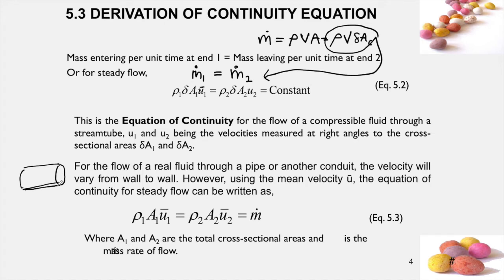So the fluid will stick at the inner wall of the pipe. From the front view, we can see that the fluid sticks on this surface of the pipe. Therefore, it affects the velocity gradient in a pipe, and it turns parabolic. So the flow will be parabolic in a pipe. You will learn this in the Hagen-Poiseuille equation.